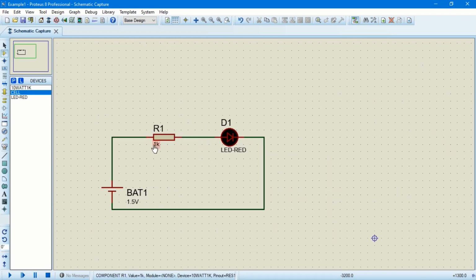After connecting this, the next thing is we want to see how this circuit will behave. This is one of the things we are going to be doing majorly in this experiment. To simulate it, come straight down to the left hand side and click on this play button. Once you click on the play button, the circuit will start simulating and you're going to see the behavior in real time. As you can see, our bulb is not coming up. I deliberately made this happen so that whenever we have a problem, we can always check it. What we need to do is to make sure all our calculations are correct here.